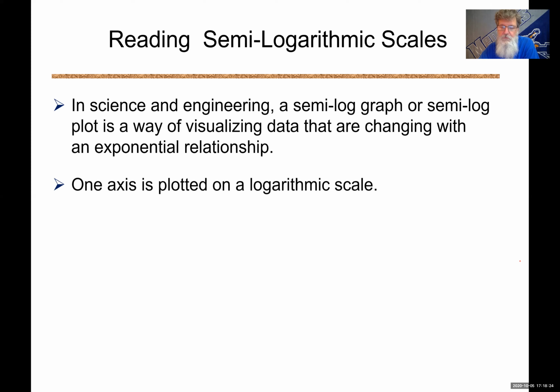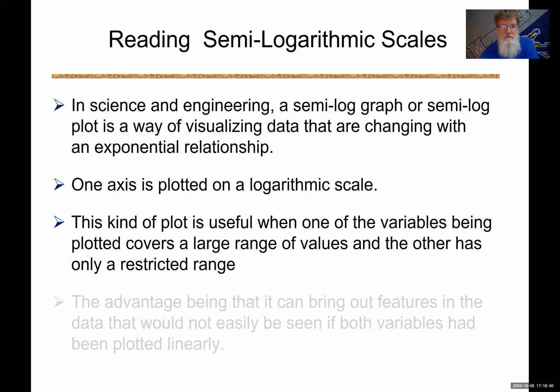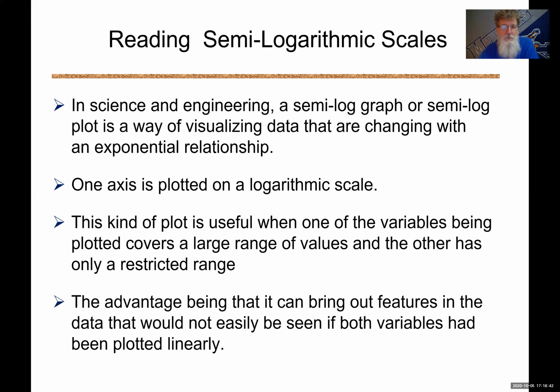In this case, we're plotting our x-axis on the logarithmic scale. This is very useful, again, when you have a large range of materials, like we showed before, going from very, very small possible silts and clays up to larger particles that you can actually see. The advantage is it brings out the features in this data that you wouldn't normally see if you were to plot it on a linear scale.